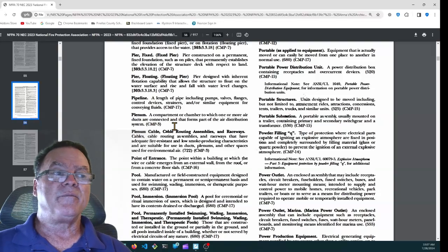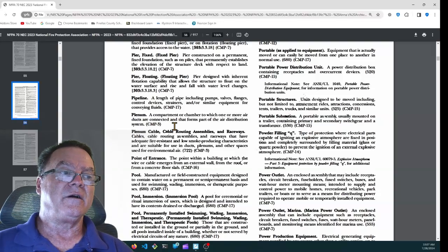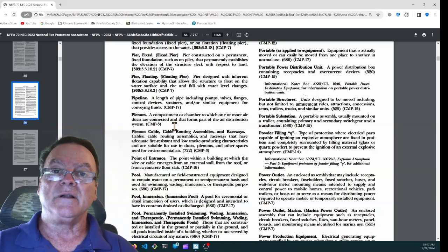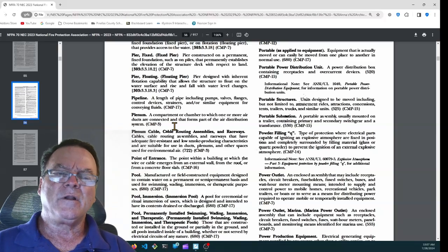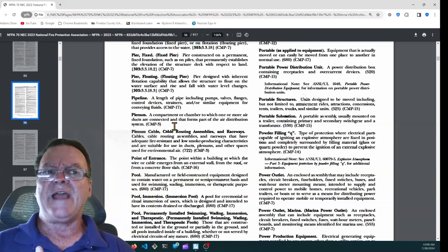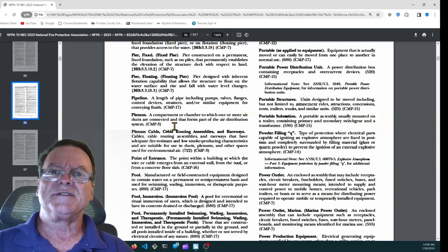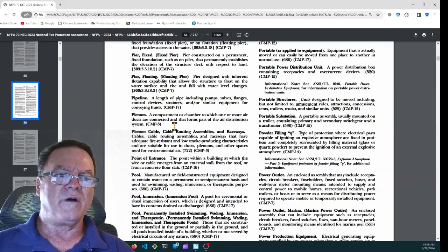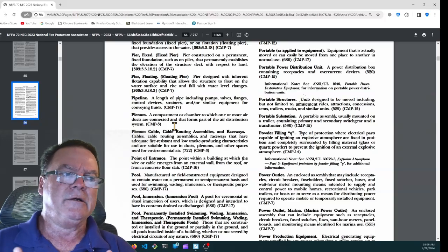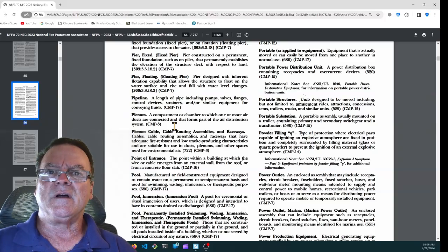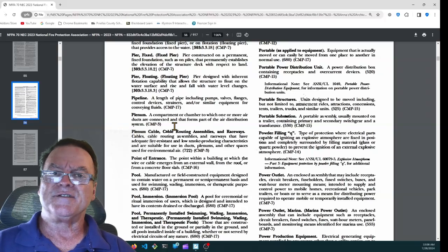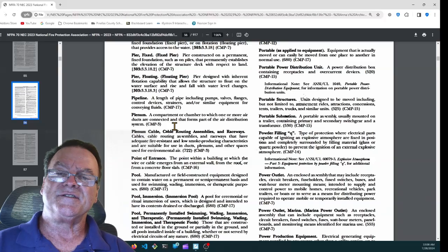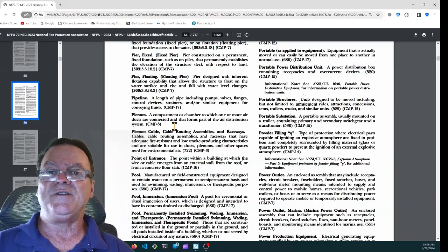Anytime we're talking about breathable air, environmental air, there are a lot of regulations that go with it. We cannot just put any wiring system in a plenum for return air or for conditioned air. If you put non-metallic sheath cable, for instance, if there's a fire, if that jacket catches fire, it gives off toxic fumes.